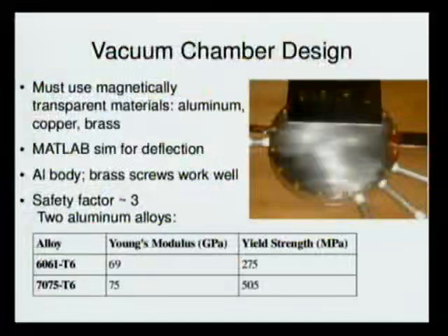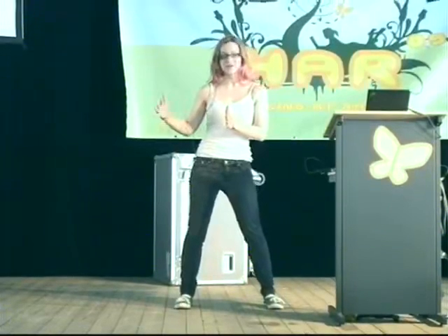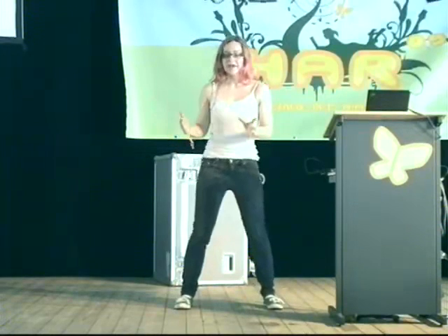Now, safety factor is another thing to consider. I feel like such a mechanical engineer talking about this here, but yeah, safety factor. It's defined as the maximum stress that the material can withstand divided by the maximum stress that the material will likely encounter during its service lifetime.